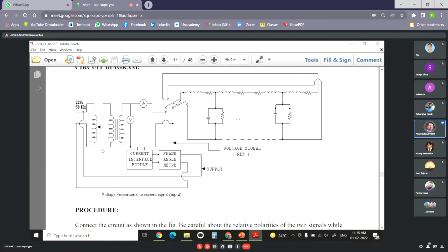So basically we'll be taking the average of the impedance values for the two voltage cases, so that our mean or average lies around the knee point of the inductor magnetization curve.